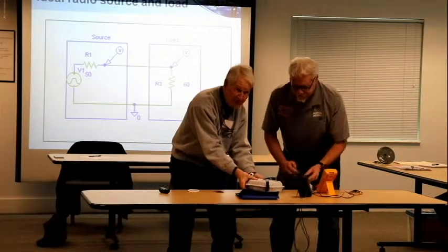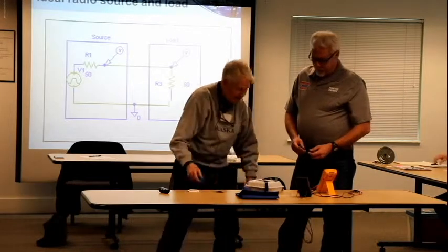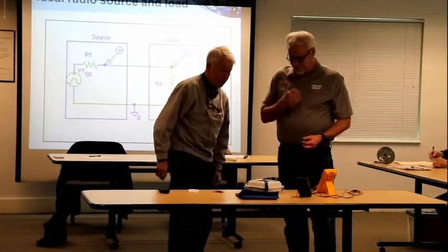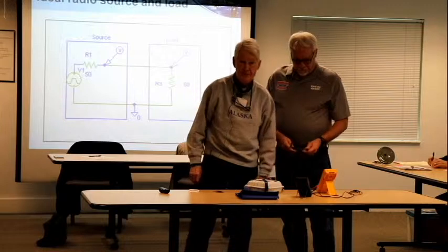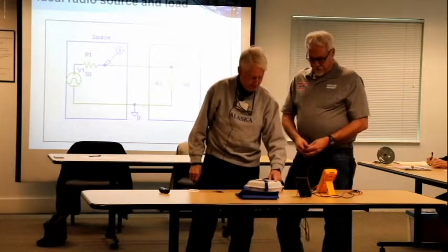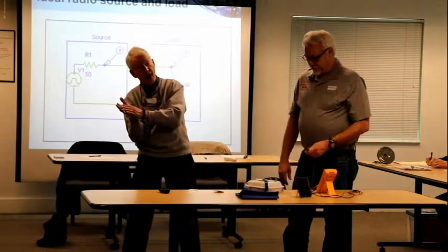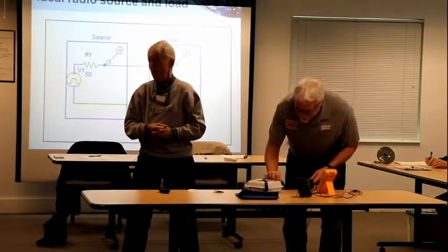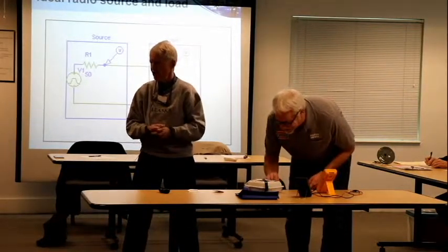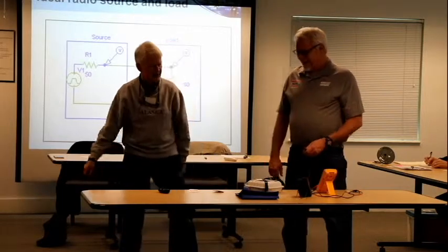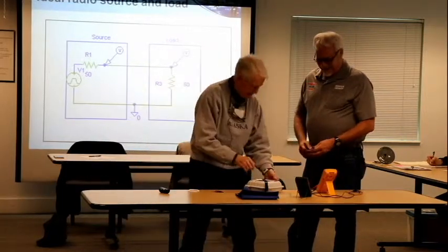So somebody write down on a piece of paper, if you've got it, 1.68 volts with 220 ohms. 1.68 volts for 220 ohms. And if you use V squared over R, you'll calculate some watts. It's such a small number of watts that it's better to measure it in milliwatts.